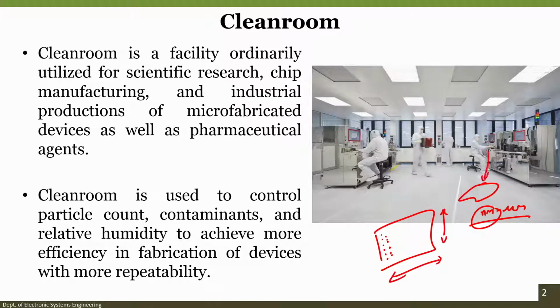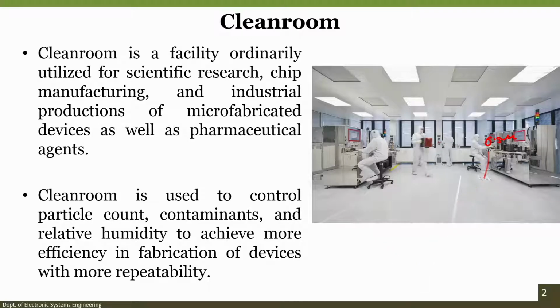But if a particle of size 0.5 micron sits on this particular chip, it looks like this. That means that 0.5 micron particle would kill a lot of transistors on your silicon chip. Same thing when you develop a drug in pharmacy: you need to make sure that the drug is free of any contaminants, and that is why pharmaceutical industries as well as chip manufacturing companies like Intel, TI, Qualcomm use the clean room environment for fabrication.